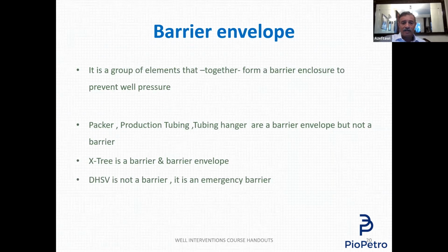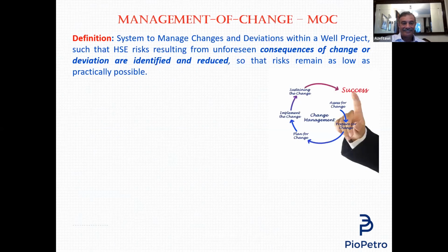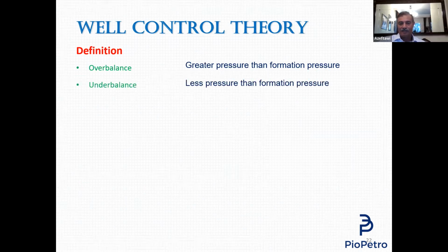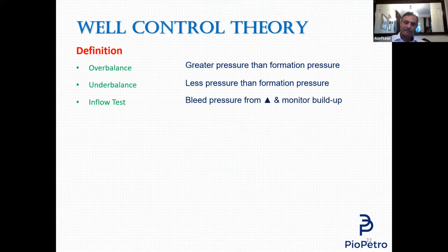Remember, this course, I teach it in 5 days, 8 hours each day, so I have to skip some items here. These are some definitions. What's overbalance? It is greater pressure than formation pressure. The opposite of that is underbalance, which is less pressure than formation pressure. In an inflow test, you bleed off the pressure above these valves, these plugs, and monitor it to see if there is buildup or not.